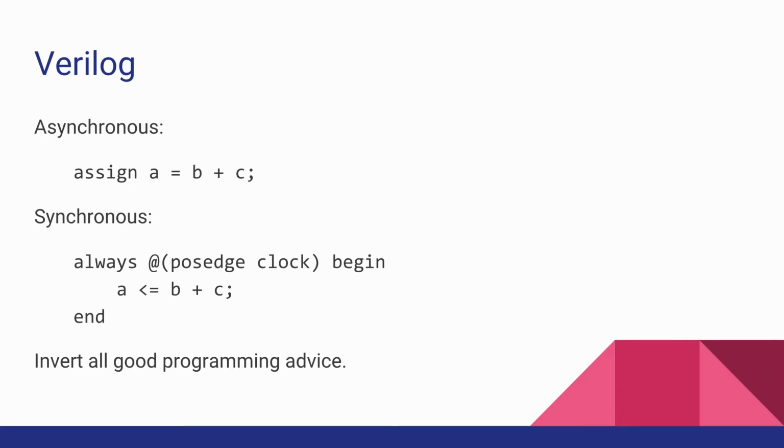So that sounds pretty good, except that A is not very clean. For example, you can imagine let's say B is 6 and C is 5. So A is 11. Now you swap B and C. Well, that doesn't happen instantly. The bits might not change all at once for B and C, and it takes a while for the signals to propagate, and then the ripple carry has to go through and do the add. So if you look at A, it's not going to be 11 consistently. It's going to be 11, and then a bunch of junk, and then 11 again.